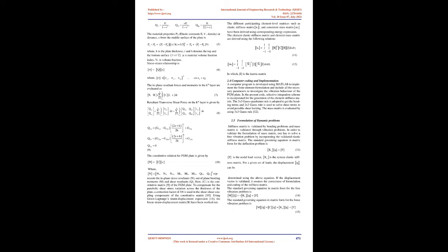The different elements of the plate are expected to undergo translational and rotational displacement. In the present work, a 9 noded heterosis element is used to discretize the plate. 2.1 Strain displacement relations. The displacement field at any arbitrary distance z from the midplane based on the first-order shear deformation plate theory is given by